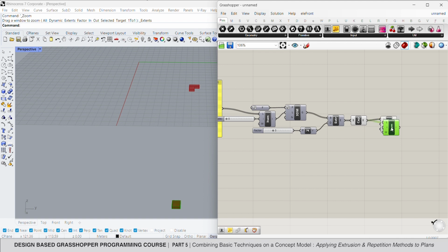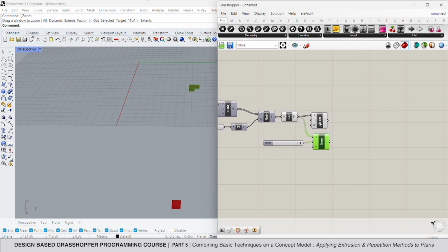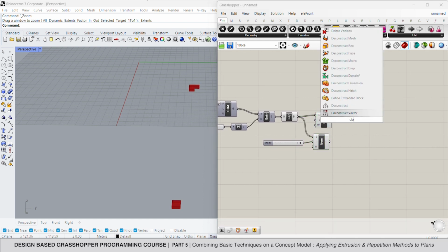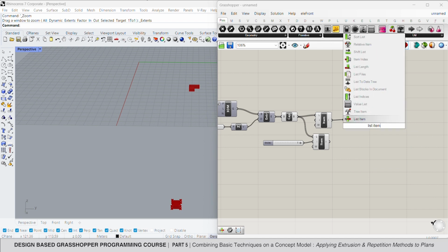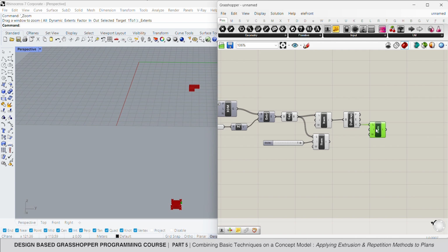To move the upper floor over the top of the ground floor, I need a base point. So let's dewrap the objects. We can use list item command again to take one of the vertices. We can arrange the indices to select the point easy to target like this.